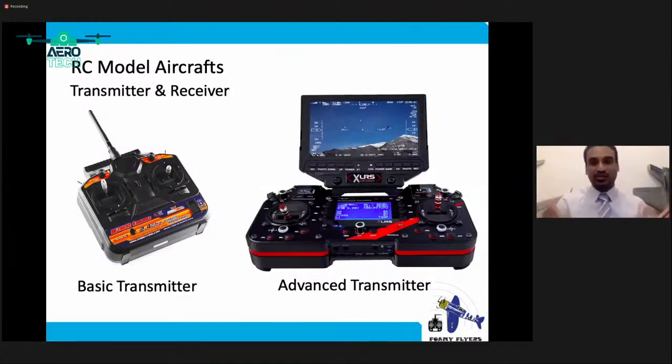But as I mentioned before, you have to get a reliable one. Off the top of my head, for reliable transmitters I would give you some manufacturer names such as Futaba, Hitec, Spektrum. Those kinds of transmitters are very reliable, and the frequencies do not jump, so you'll have a fixed connection and you would not have issues with signal loss. However, I have mentioned that this has to be reliable.